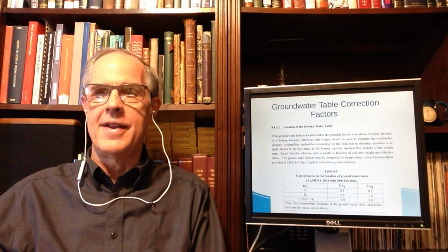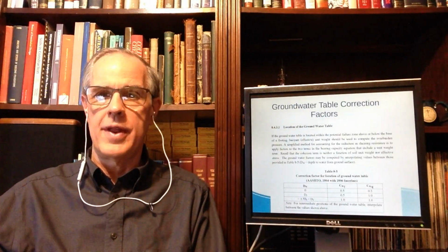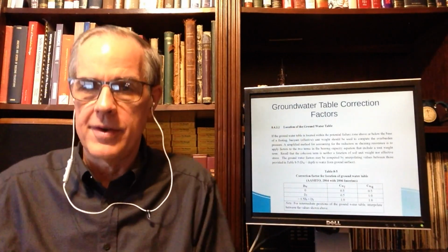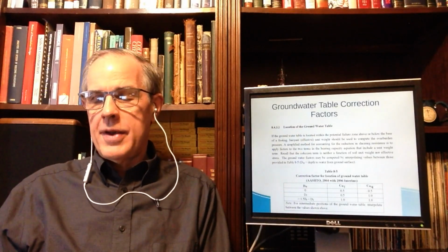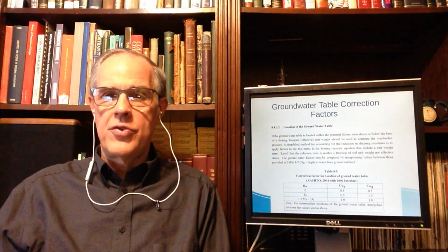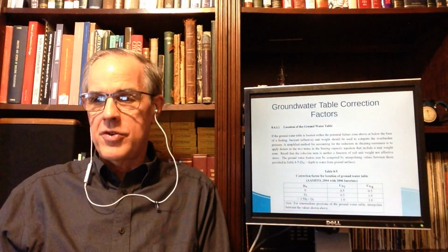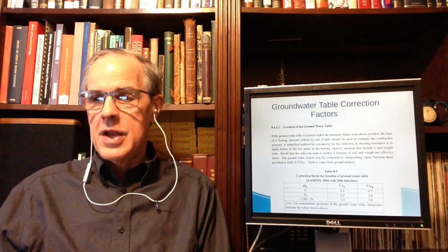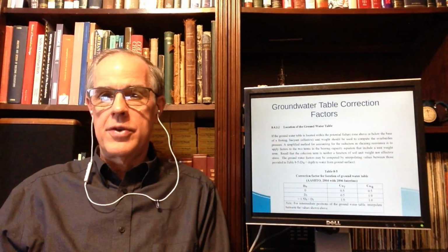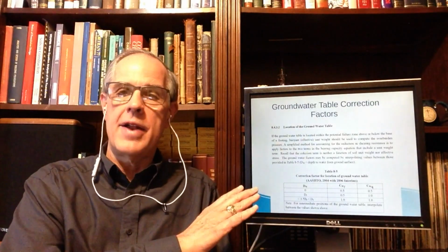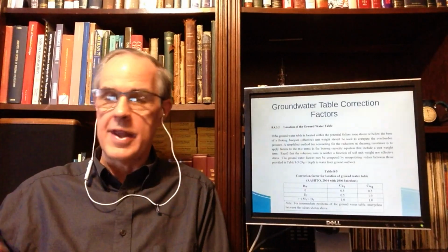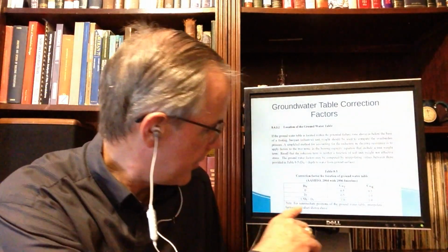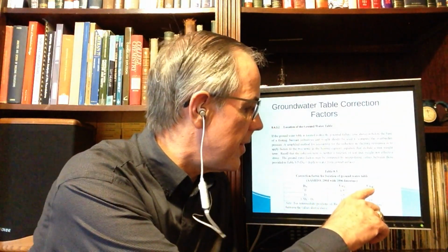We'll talk about that in deep foundations, is where that really comes into play, where challenging that comes into play. But in any event, if your groundwater is at the surface, DW is 0, then it doesn't apply to the cohesion term. It only applies to the Q and the gamma term. And you'll see they've got CW gamma and CWQ.